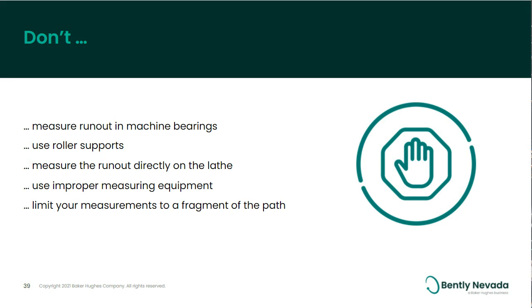Any eccentricity in the rotor supports can cause mechanical runout that can't be seen when checked in the same support structure. If the rotor support has an egg-shaped travel path due to bearing wear, the rotor will be egg-shaped when it's machined. But because you'll be looking at it in the same machine that machined it, putting a probe there, it's going to look perfectly round. Always have it in a separate machine, either with V-blocks or in a balancing machine, something that is a new measurement reference to make sure that you're getting an accurate measurement there.